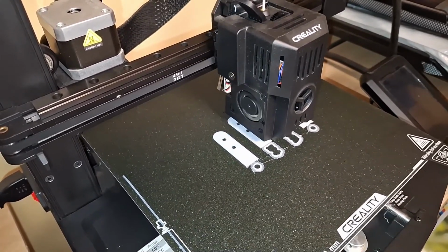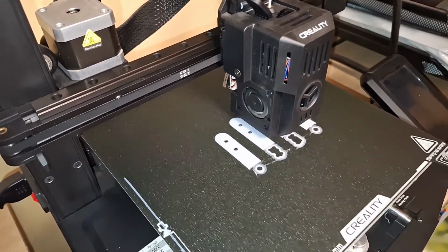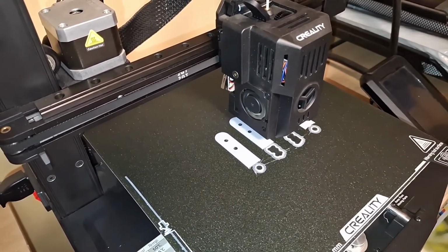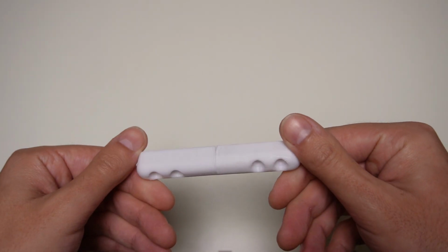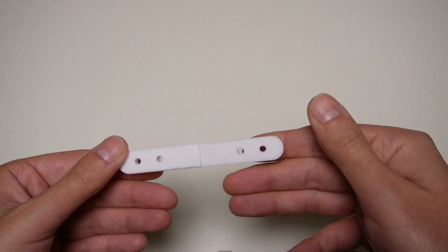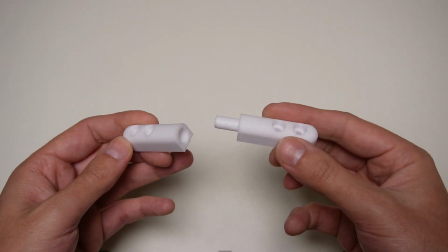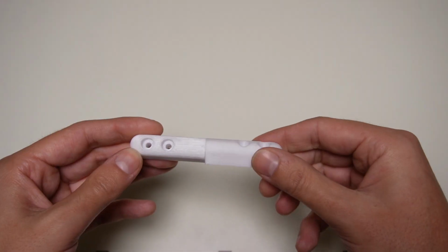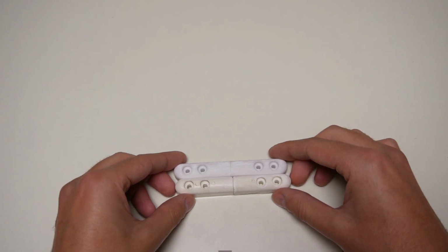To print both halves, I used 3 supports under the pin and inside the hole. As a material, I chose to make them out of PETG filament because it is suitable for outdoor use. And here you can see both halves once again. The pin must go freely into the hole, so you have to clean the rest of the support nicely. And here you can compare it to the old hinge.